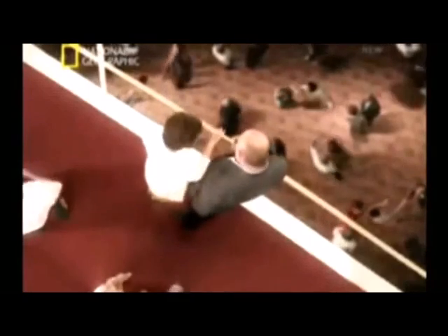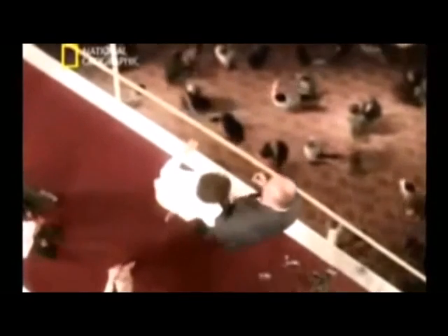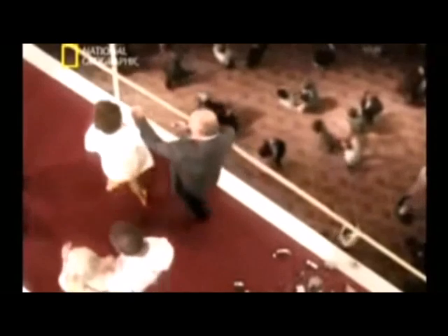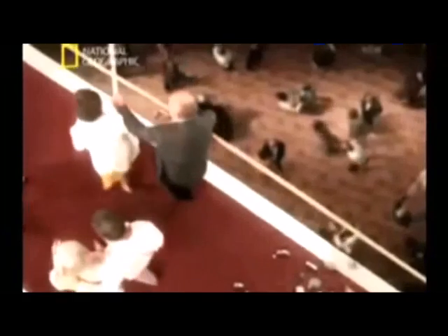As the restraining nut smashes into the top of the beam above with a sharp crack, the walkways drop down sharply. 2 seconds later, disaster strikes. The box beam fails. The remaining connections on the third floor instantaneously unzip. The third floor walkway flies down at over 15 meters per second. 65 tons of concrete and steel crash into the lobby floor in just 1.6 seconds.